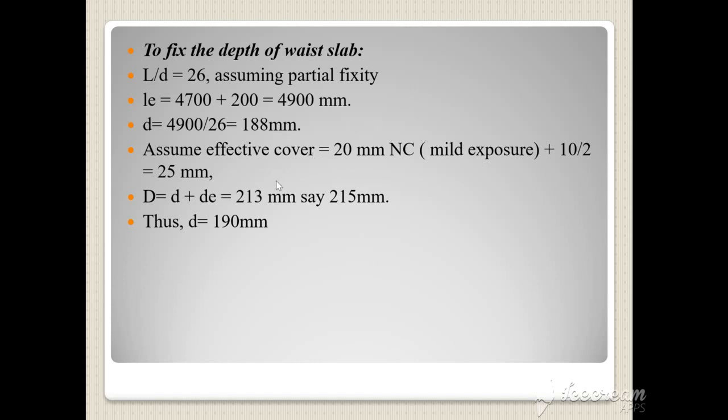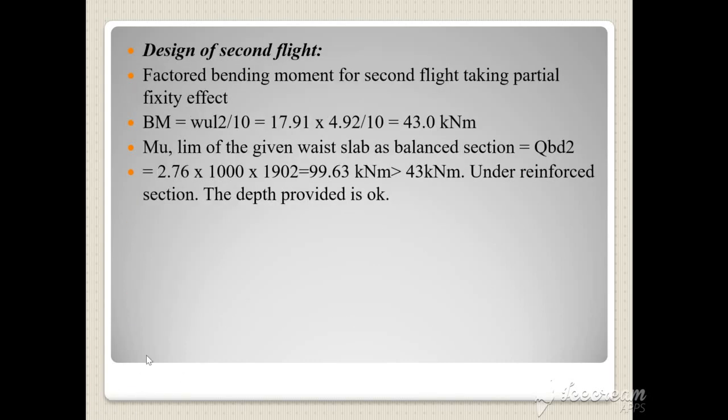So it is coming around 213. So let's provide 215 mm, this overall depth. So based on this overall depth, we need to just decide the effective depth. Effective depth coming is 190 mm. So this was your effective depth criteria.